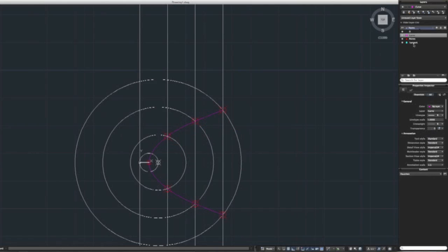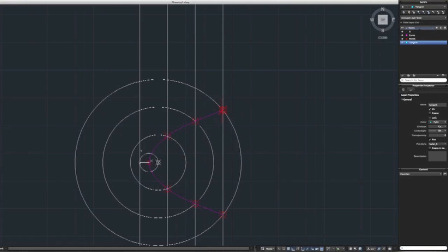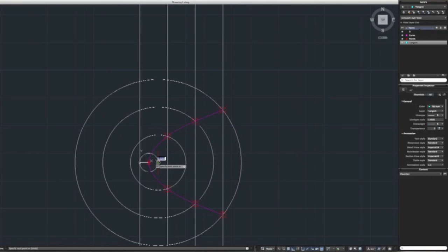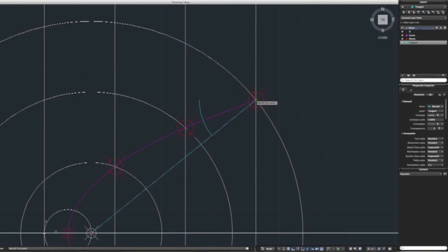Now let's make a tangent with the top point up here. So what you can do here is, by starting at your focus point with a small line, connect it with your top line, and then make a straight horizontal line to your left, like that. Next up, select a circle and place it about here. The radius does not need to be a specific dimension. And now let's select these lines and trim the outer part of our circle.